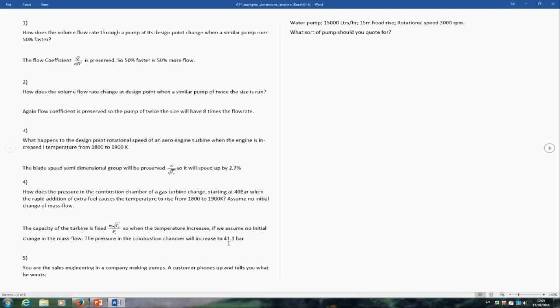And what this can do is to push the compressor up its characteristic towards surge. So you make it go to low flow, it becomes unstable. This is called fuel spiking, and in industry we test compressors by squirting in additional fuel to make the pressure rise, to make the compressor move up its characteristic towards stall and surge. And if you squirt in the fuel and the compressor then goes bang, bang, bang, you know it's unstable.